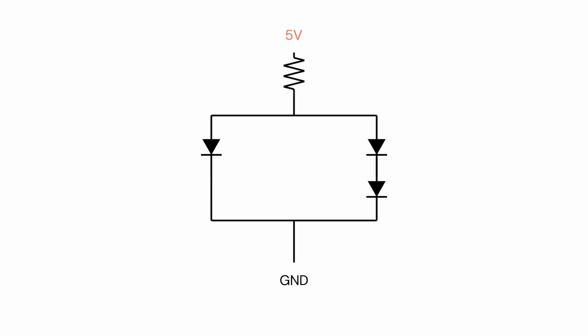Let me show you an example of analysis that showcases a design technique called current steering. Imagine you have two paths that the current could take that go over p-n junctions in diodes. The voltage drop in each path is different, and we'd like to know which path is taken. If the current takes the left path, the voltage at this point should be up arrow. If it takes the right one, the voltage will be 2 up arrows. The voltage can't be both, so it means that the current is taking only one path.